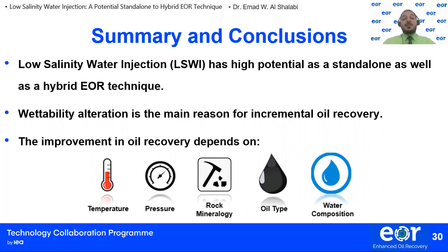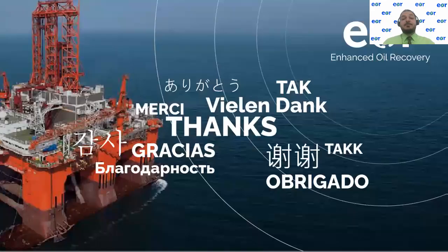A very important thing to stress is that the improvement in oil recovery using this technology is really case dependent, and you need to understand those factors before you can expect a pronounced effect. Those factors are the temperature, the pressure, the rock mineralogy and initial wettability state, the oil composition, and most importantly, the water composition.